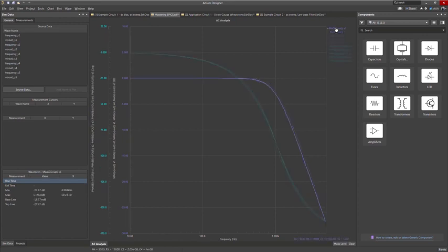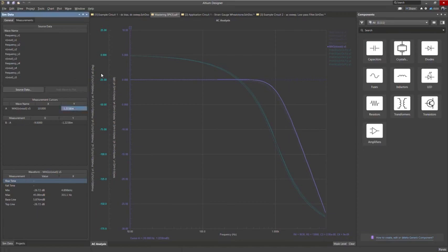So if we take a look at my magnitudes and focus at the bottom right here of this plot, we see the different combinations of my resistors and capacitors and how these different combinations give me a specific output, right? So I could start looking at these, and if I look between S4 and S5, the resistors aren't changing, yet I'm getting a change in my cutoff frequency. So that's telling me that my capacitance is really changing this cutoff frequency.